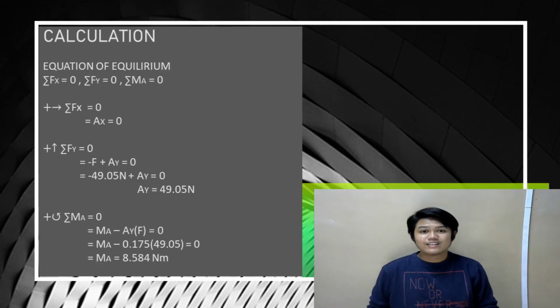Thank you. Calculating the reaction at supports is always the first step in analyzing this structure, and it is generally the easiest. It involves calculating the reaction force at the support due to the forces acting on the structure. When solving a problem like this, we first remember that the structure is static, meaning it is not moving. From simple physics, this means that the sum of the forces in the y direction is equal to 0. That is, the total downward force equals the total upward force. A second formula to remember is that the sum of the moments about any given point is equal to 0. This is because the structure is static and therefore not rotating.